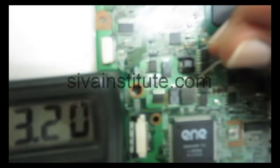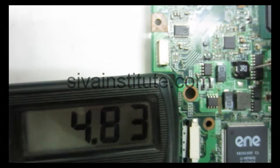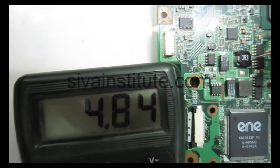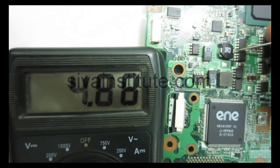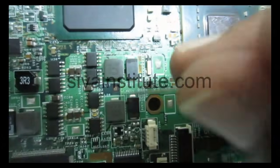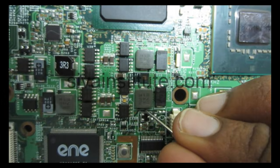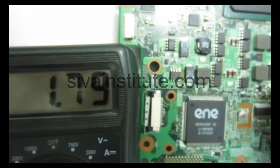Next, see at that coil, 5 volts. See 5 volts. 4.7, 4.8, okay, 4.9. This voltage is okay. 3.3 volts and 5 volts are okay. Now we will check the memory supply 1.8 volts. 1.8 volts at this coil. Okay, 1.8 volts memory supply. 1.79, that means 1.8 volts.